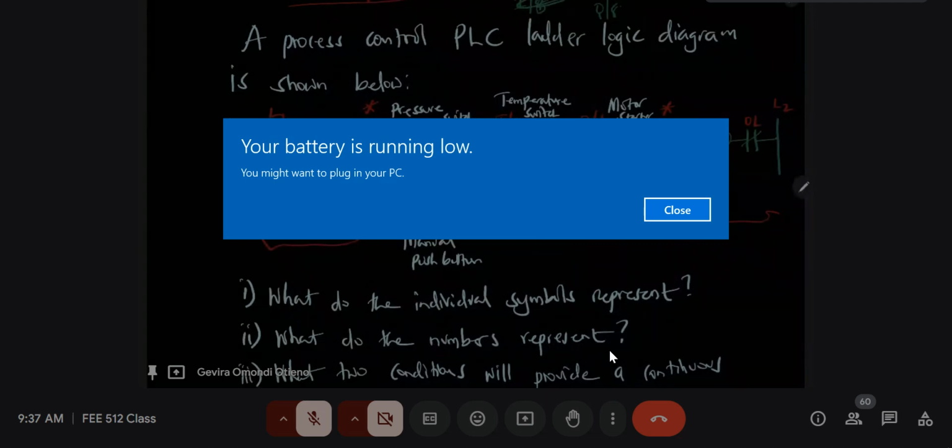Remember, see how it's drawn nicely. The program is I1. Let's look at the first normally open contact. It's I1. And our switch, the physical one, what we were calling the field devices, is also labeled I1, meaning that now the PLC module, remember we were talking about the components of a PLC, and we said that there are input modules and then there are output modules.